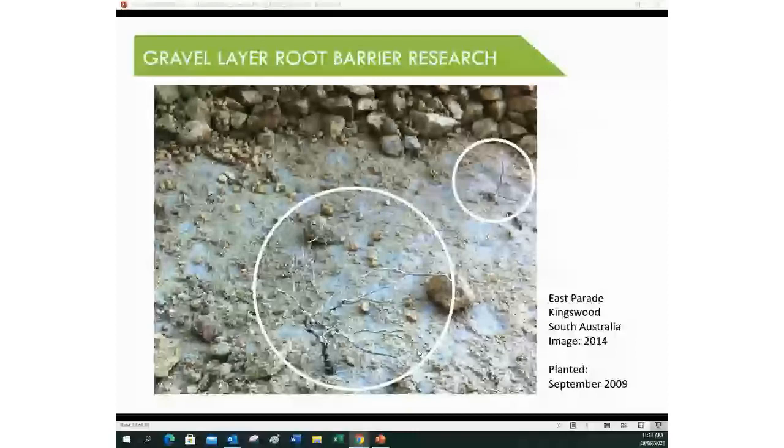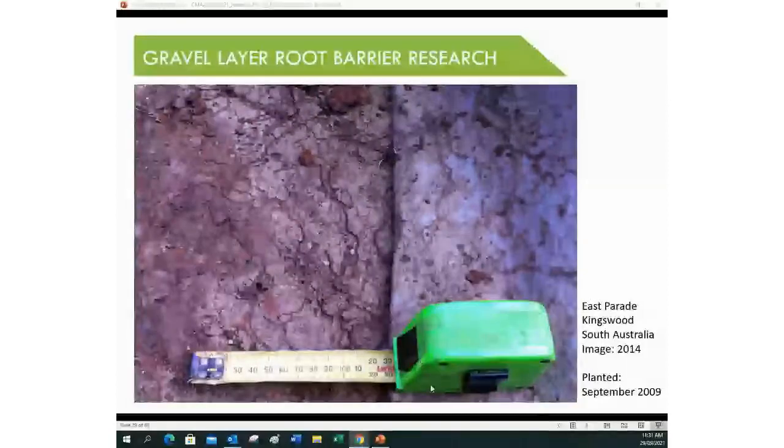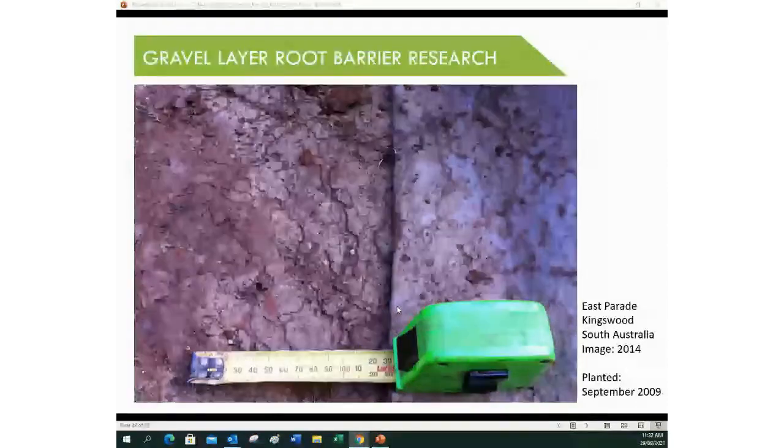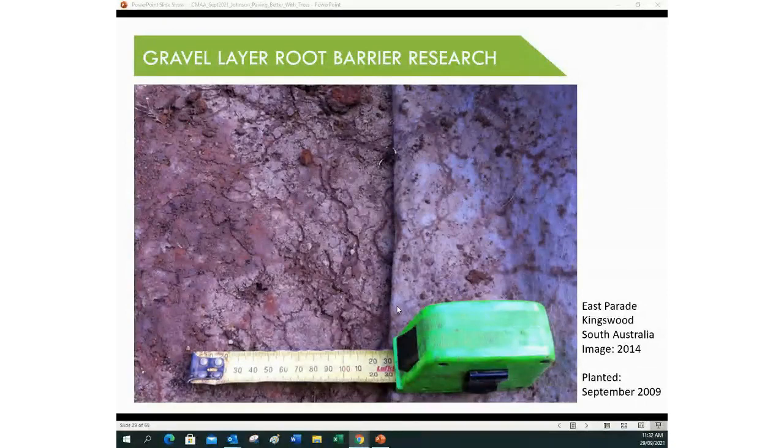We didn't stop there though, looking at the gravel base. If you lift the geotextile, see all these tracks where the roots have been. There's very few roots left here, but there's a lot of evidence where they've been. That's just further evidence of this fine root turnover. That's really what we need to work with. If we can restore natural conditions in the pavement base by having it ventilated, allowing water and air through, we can restore this fine root turnover. And it actually allows the surface of the subgrade here to desiccate over the summer as well. So the subgrade surface doesn't support root growth.